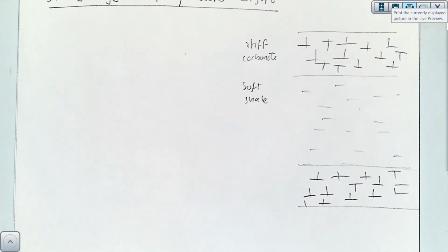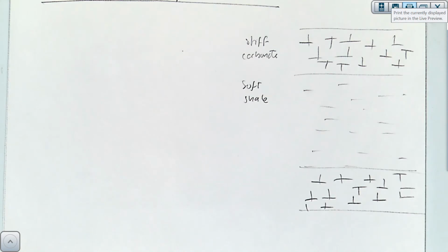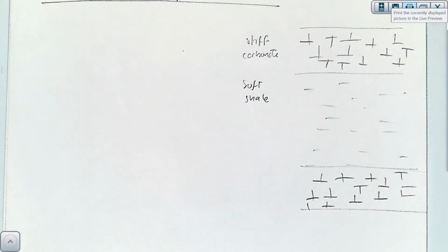How can I measure the properties of rocks in the subsurface? How can I tell if the rock is stiff or not without taking any samples and doing any laboratory tests? The density is going to tell you the mass density, but it's not going to tell you how stiff the rock is. So you would use a sonic, right?